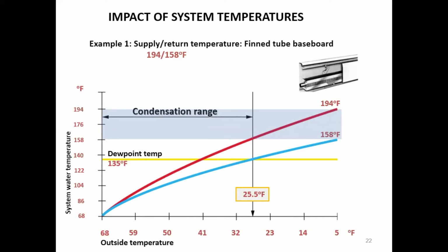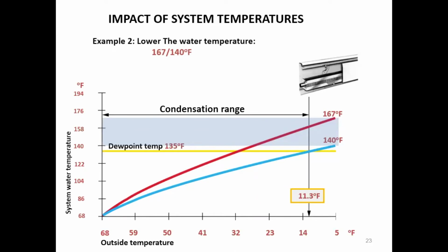Okay. Now, if the opportunity exists, whether I'm designing for air handlers, or for heat emitters with lower return and supply water temperatures, or an existing building has the opportunity to drop the water temperature, for instance, when the building envelope has been improved as well as the heating plant being upgraded. If I can drop from 160 down to 140 degrees, that crossover point all of a sudden changes from happening on a 25-degree day to happening on an 11-degree day. I've picked up more of the heating season where the boiler will run in a condensing mode, and every day of that heating system, the boiler is going to run more efficiently. So from a design standpoint, if I can design for a lower water temperature, I can then start to drive efficiency even higher. This is where radiant shines.